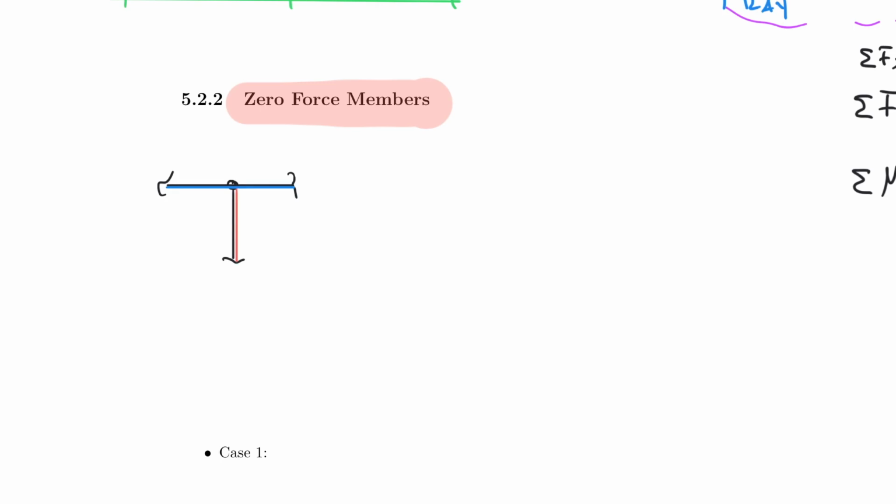This one here actually happens to be not random. It's actually perpendicular. But remember that for this case here, it's easier to see that any force that is acting perpendicular to this system cannot be resisted at this node because you cannot create equilibrium here. So let's say you pull on this member, it's not resisted up here. So therefore, you only have one force in one direction, and therefore you cannot create equilibrium. That means that this member here must be equal to 0.